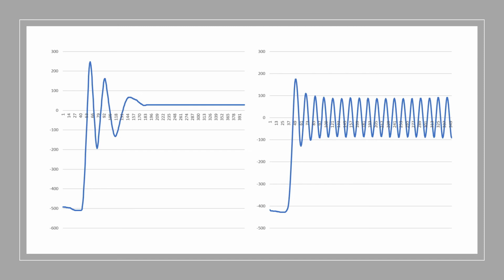With the P controller, if the step input is high, the KP is better when it's low, because it will limit how much we can increase the gain. Therefore, it can become unstable easily. You can see on the other side, we increase the KP to 15, and due to the fact that the step input is 200, which is high, there is a constant oscillation, and it is not settling. The wheel has refused to reach a steady state, and the system has become unstable here.